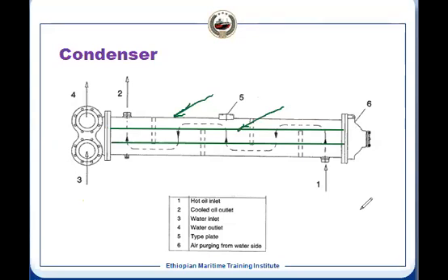Because it is trying to expand, we are restricting it from expanding. It means there will be a strain, which can affect your material, and the material can fail. So that is the reason we need to allow the differential thermal expansion. Now suppose due to the temperature increase or decrease, it can increase. If it is increasing, that is expansion; if it is decreasing, that is contraction.